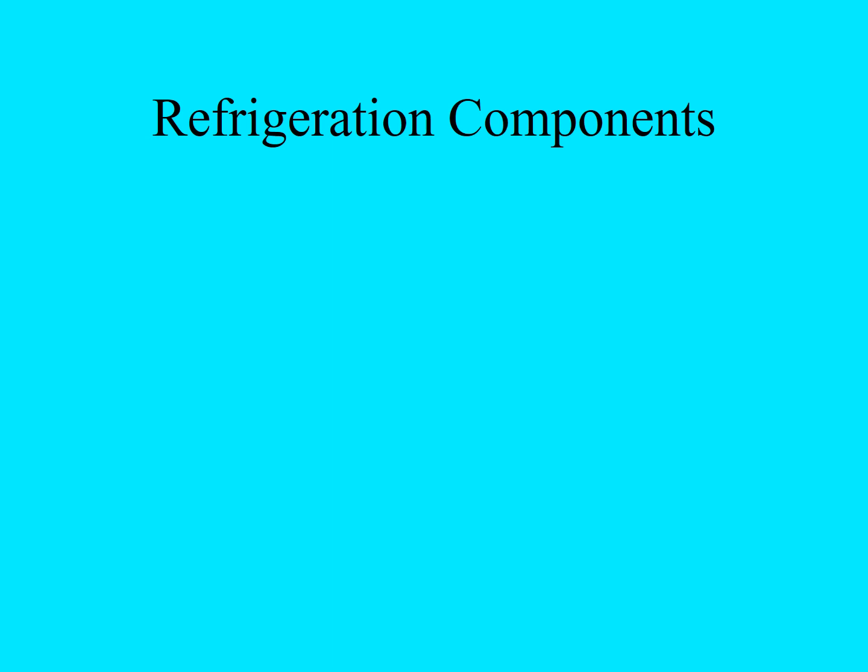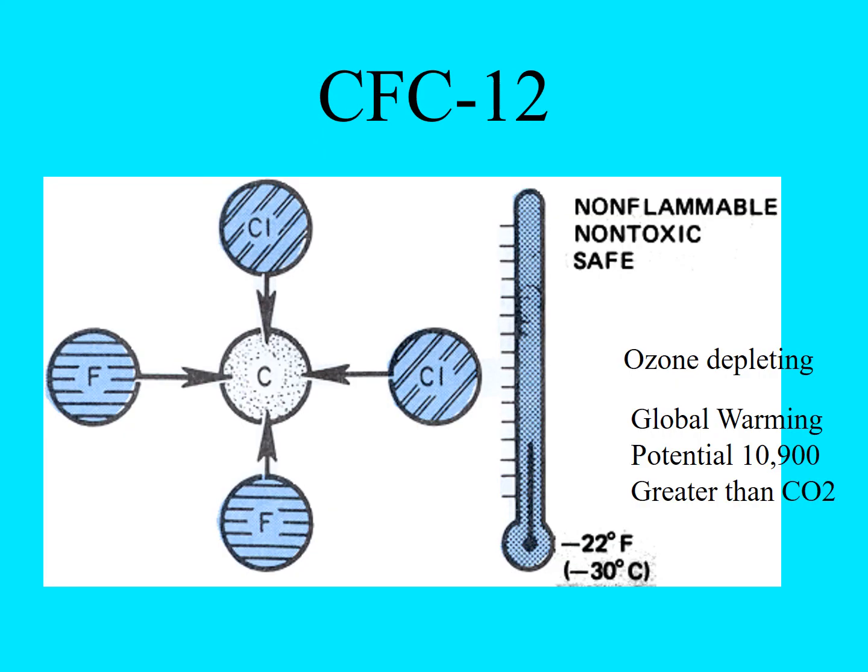So refrigeration components, we'll start with the refrigerants because there's 4 refrigerants that have been used or are being used. So CFC 12 is no longer being produced. Okay, this was the first refrigerant manufacturers used for the refrigeration systems in automobiles. So, as non-flammable, non-toxic, pretty safe.